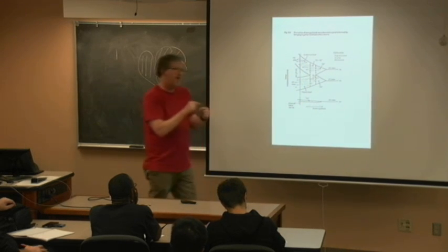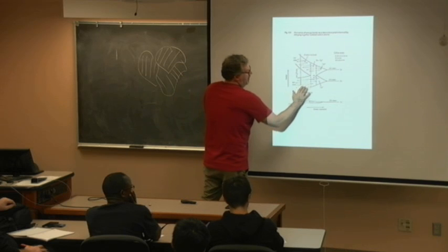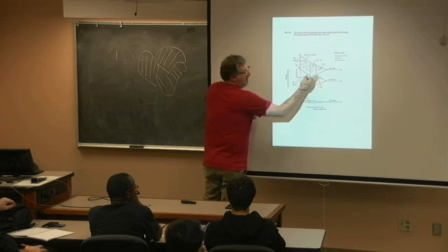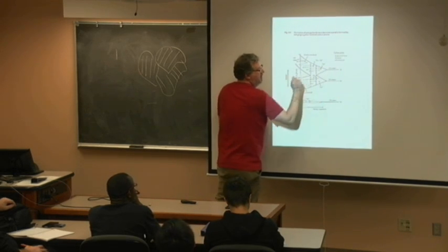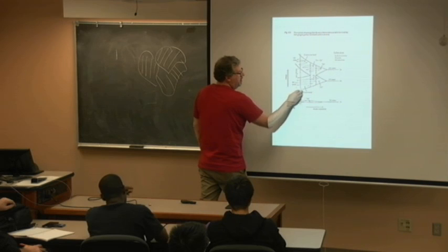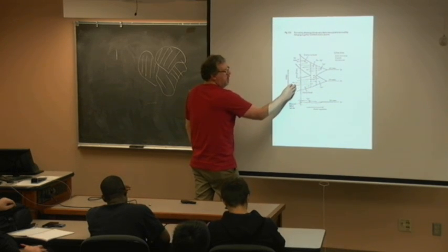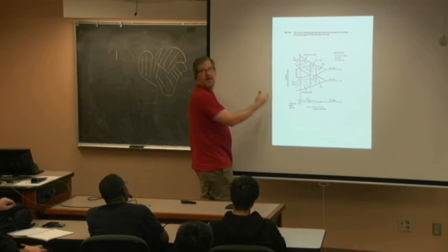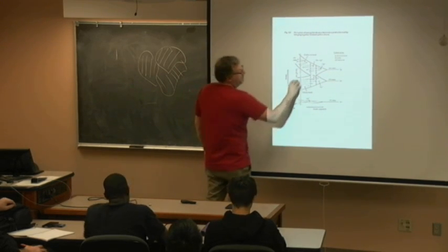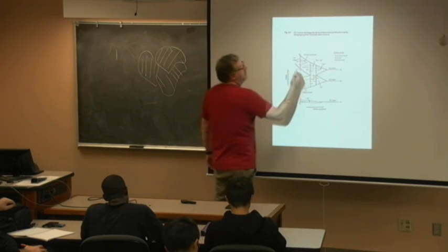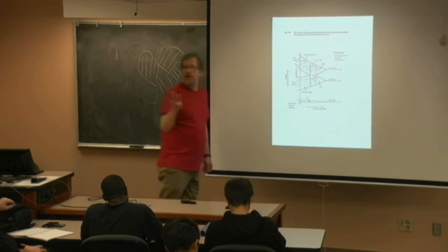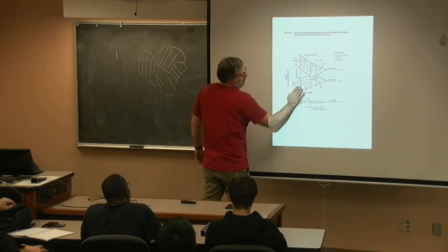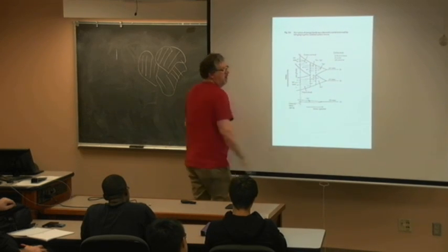And now the interatomic spacing is such that the splitting of the energy levels has manifested, so that the 2 states in the 2s and the 6 states in the 2p have merged and blended, and 4 of those have come down here, and 4 of these come out, because 2 plus 6 makes 8, 4 plus 4 also makes 8, so I have a conservation of energy levels. And in silicon or diamond or whatever, I have 4 valence electrons. So I've got 4 gumballs to put into this, 4 electrons. And so when I fill up the valence band, I run out of carriers.